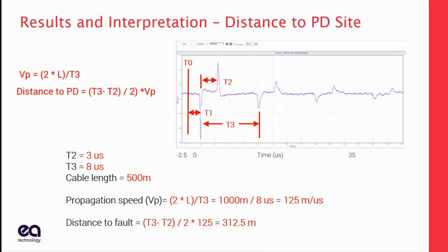That action may be replacement, it may be offline testing, it may be live with it, but I know I've got redundancy. Whenever you can get a distance to a PD event in online testing, that's just a bonus. It makes your life a little easier, but that's not really the goal. The goal is to screen high volumes of cables easily and quickly.